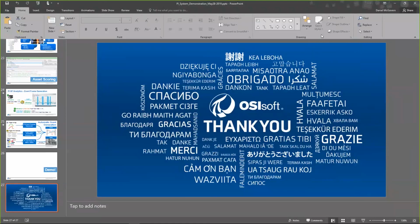We have what's called the PI audit tool, which is a system that runs and tracks any change to any tag configuration or tag data, so that if there is ever any recalculated data, updated data, or backfilling of data that was lost, not immediately available, or was marked as bad data but was recovered from somewhere, all that visibility is maintained. With any sort of reporting, you can always trace back and say, here's exactly what happened here. So I would urge you to look up the PI audit viewer and PI auditing tools, but we can definitely provide more information on that.